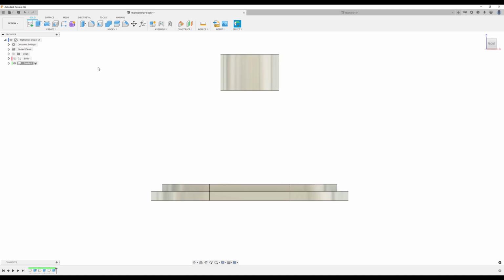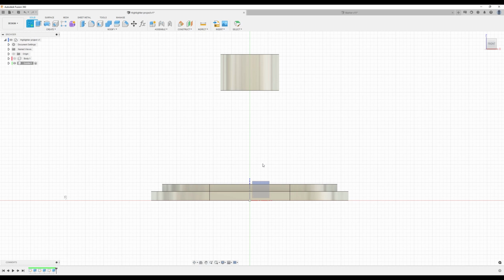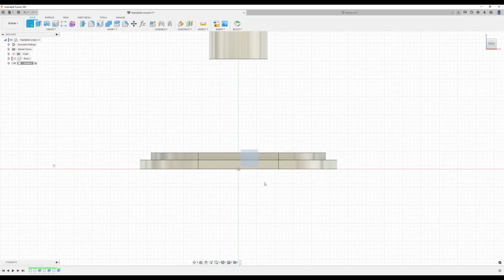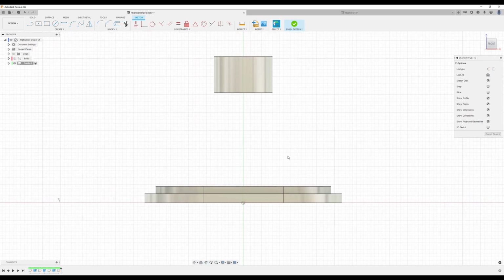All right. Now what we want to do is create another sketch on the front plane. Select the plane axis here. Okay. All right. We're going to use the project tool because we want to project some lines to assist us. We're going to select this line, this edge, and this edge. And make sure that selection filter is specified entities, not bodies. Projection link is turned on and click OK.